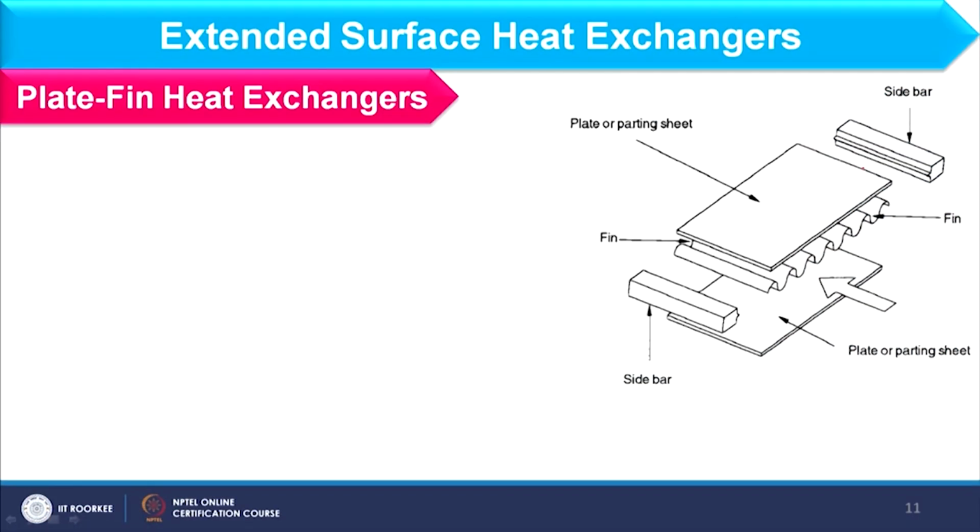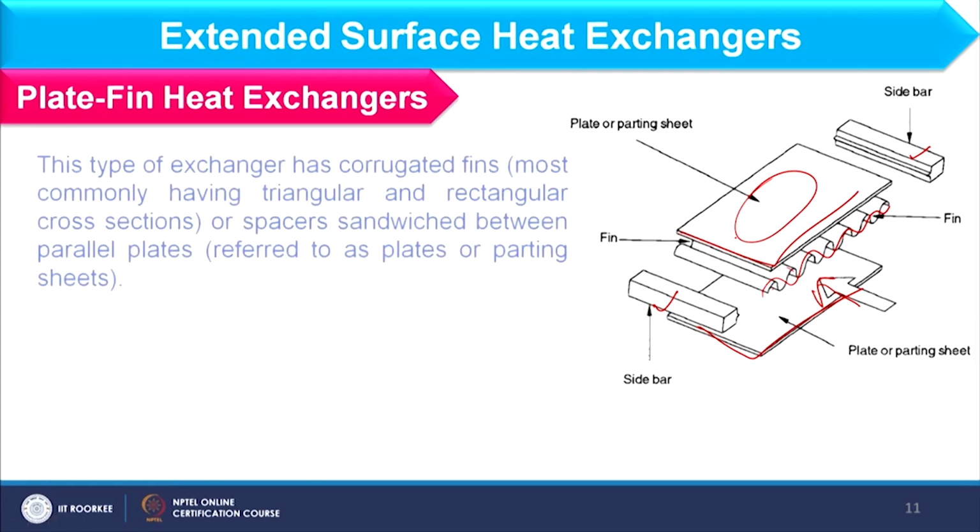And now we will focus on extended surface heat exchangers. If you see here, we have the schematic of this. Extended surface means we are basically using fins. And these fins are placed between two plates. If you see, these two plates are there and fins are in between, and at the side we have the side bar. Inside this fin we have one fluid, and another fluid would be over the plate. So, this is basically the plate fin heat exchanger.